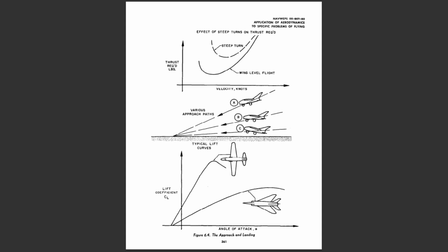For example, if it is realized that the airplane is above the desired glide path, a more nose-down attitude without a decrease in power setting will result in a gain in airspeed. On the other hand, if it is realized that the airplane is below the desired glide path, a more nose-up attitude without an increase in power setting will simply allow the airplane to fly more slowly and, in the region of reversed command, eventually produce a greater rate of descent.